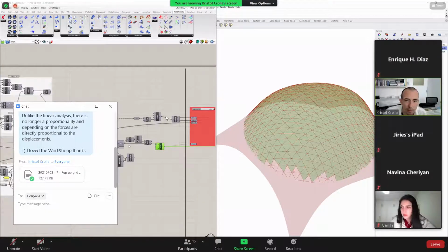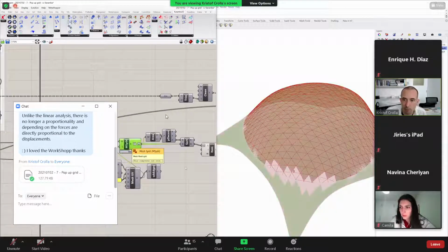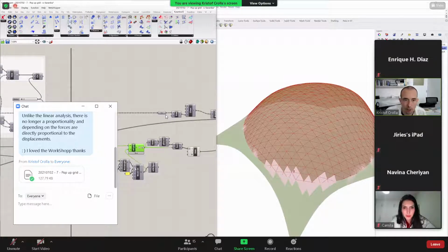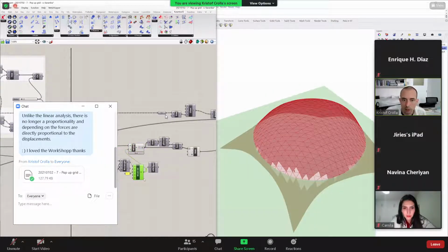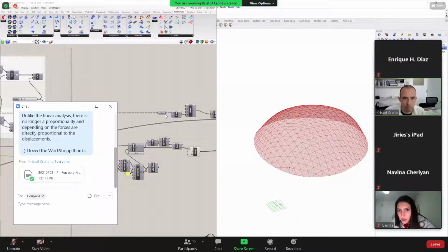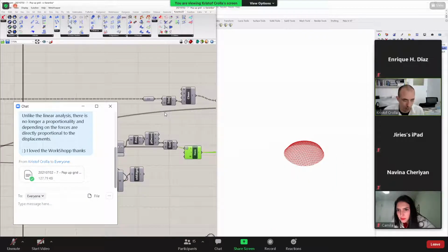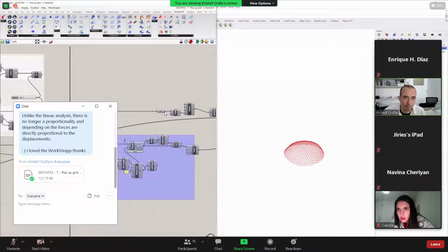Hold on, I split my mesh based on a plane. So I used the mesh split tool, which basically cuts the top mesh based on that mesh over there. And oh no, maybe it's just a graphic glitch. Yeah, it's just a graphic glitch. So I'm basically just splitting my top mesh based on a large plane that's on my ground plane, and then I'm only taking the upper part of that mesh to calculate with. So that's a very straightforward part here. Mesh split.